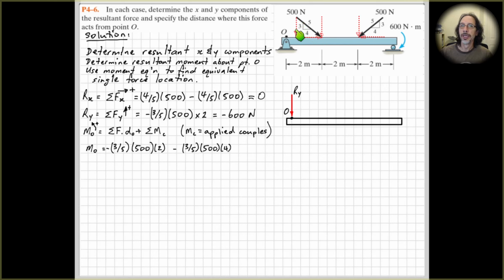Because in most engineering problems, we have to work out moments. Drawing your component over here, instead of where it properly acts along its line of action, can be a little bit confusing or misleading when you calculate the moments. We're looking for the perpendicular distance, which is 2. If we've got our force component drawn over here, it doesn't look like it's 2, if you've got the component here. So draw it where it properly acts.